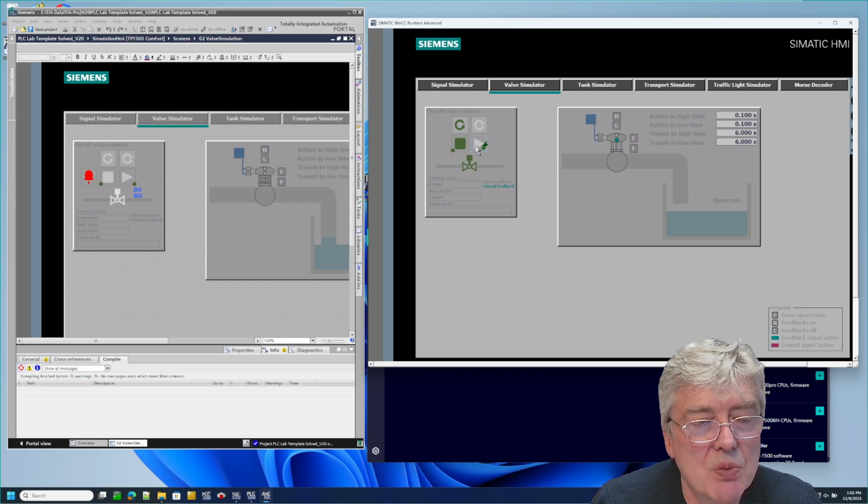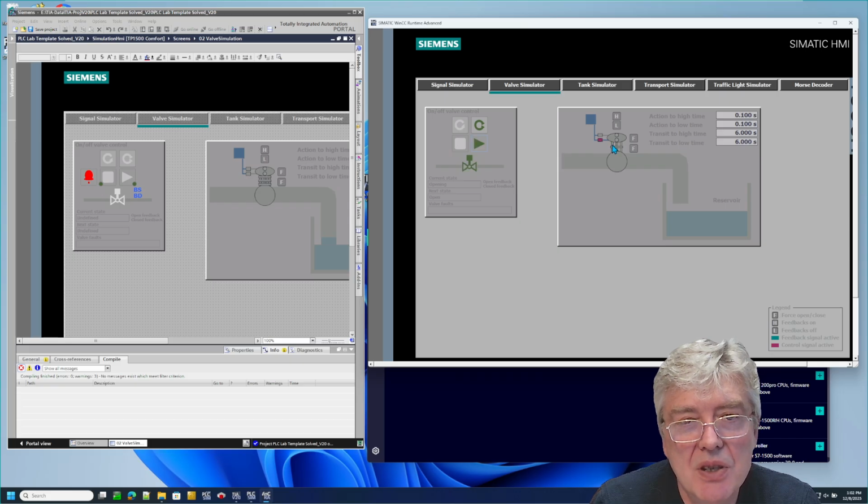So close doesn't work. So here was a command. We didn't look at it, but the command was here for set bit for manual mode. I think that was the one we looked at. Now in manual mode, and now this one should work. Okay, it works. Here was the command out. So it's trying to open, it's pushing air in here and opening the valve, and now we have got a flow.